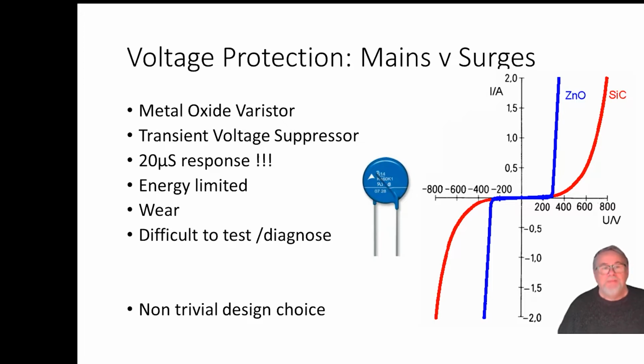But you have to put them in because very often, if you're designing a piece of equipment, you have to meet the UL spec or the CE spec, and those specifications will say that your device has to be able to withstand a 700 microjoule impulse, or a spike that lasts for up to 35 microseconds. And you have to actually put these devices in to pass those standards.